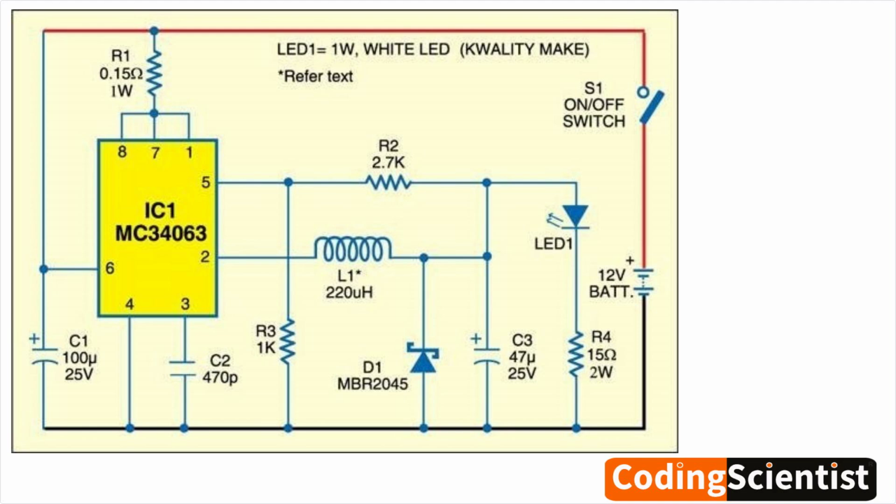LED1, 1W, white. This is the high-power LED that the circuit is designed to drive. S1, on-off switch. This switch controls the power to the circuit. Switching cycle. The MC34063 operates in a switching mode, turning the power transistor on and off at a high frequency.